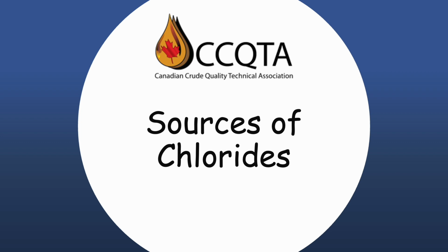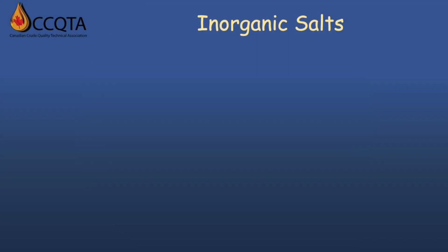By comparison, organic chlorides are considered non-native to crude oil and assumed to be the result of contamination during production or transportation. Known sources of contamination include waste oils, cleaning solvents, and dry cleaning fluids. It is also worth noting at this point that certain crude oil production processes, such as acidizing, fracturing, and unconventional production techniques, can also lead to organic chloride formation, which then does challenge the assumption that organic chlorides are not native to crude oil. Let's start with inorganic chlorides.